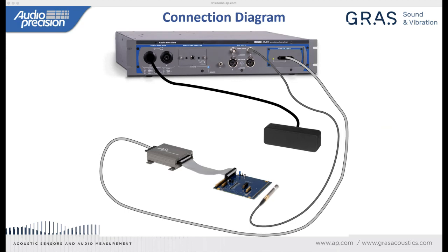So one question is, PDM microphones have gotten quite tiny, and they are indeed. The PDM microphones are actually often smaller than even a 1/4-inch mic diaphragm. And positioning the reference mic at the exact position raises some challenges, and it makes accuracy challenging. And how do we cope with that? Number one, I want to observe that is exactly true. The MEMS microphones have gotten extremely small, which is frankly a benefit for them.